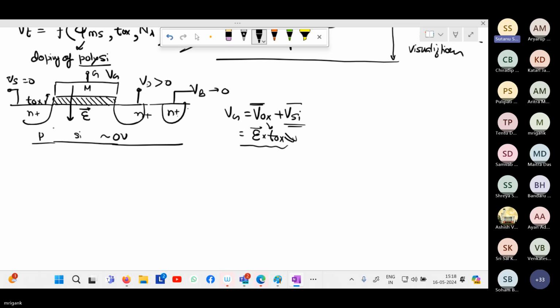Generally the p-type silicon will have holes all around. The uniform hole density will be there, which will be dependent upon approximately the doping concentration. So if you have concentration Na equal to around 10 to the power of 15 per centimeter cube, you will have that many holes in that piece of silicon, depending on the dimension and the doping concentration.